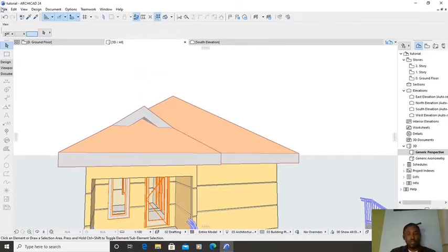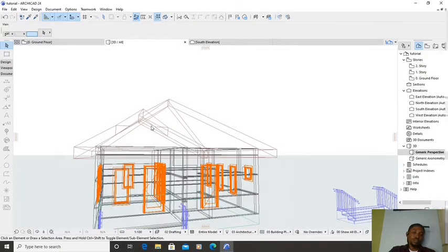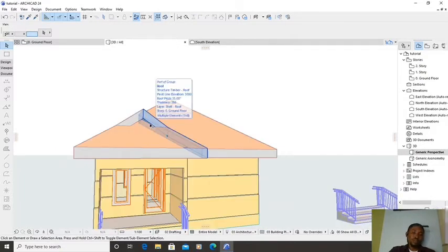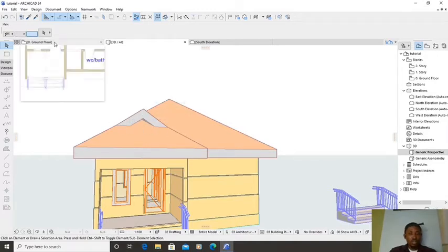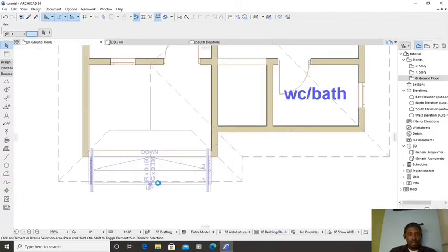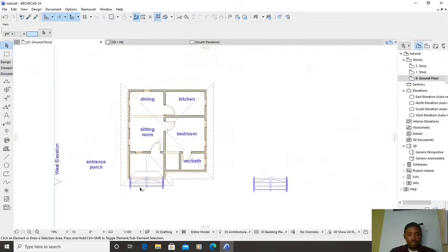Most times people leave it this way. Most times some people cover this place with either vent material, or what we call sun breakers. We cover the sun breakers to prevent rodents from having access inside the roof. Get it? Okay, I don't know if this tutorial is useful for you. This is how to do your roof, your multi-plane roof.